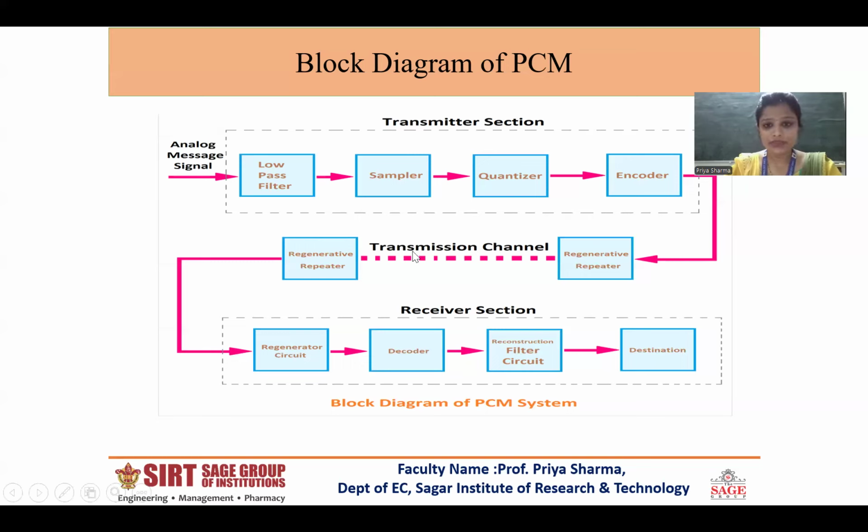In the pulse code modulation receiver, the regenerator circuit is followed by the serial to parallel converter, which converts the serial pulses received from the transmission line to parallel pulse code modulation codes. The digital to analog converter, or the decoder, generates a sequence of quantized multi-level sampled pulses, resulting in reconstituted pulse amplitude modulated signals.